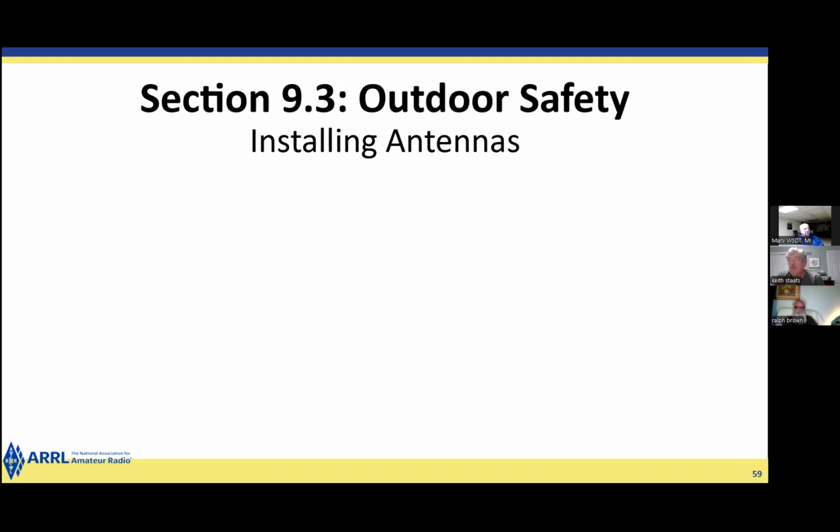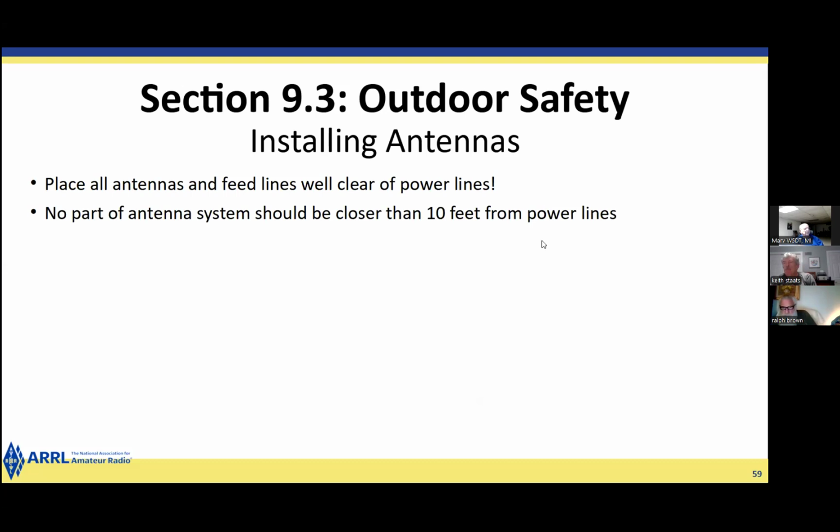Okay, outdoor safety, installing antennas. So, as we've been talking, place all antennas and feed lines well clear of power lines. It's a biggie. No part of an antenna system should be closer than 10 feet from power lines. That answers your question from earlier, Ralph. Yeah.